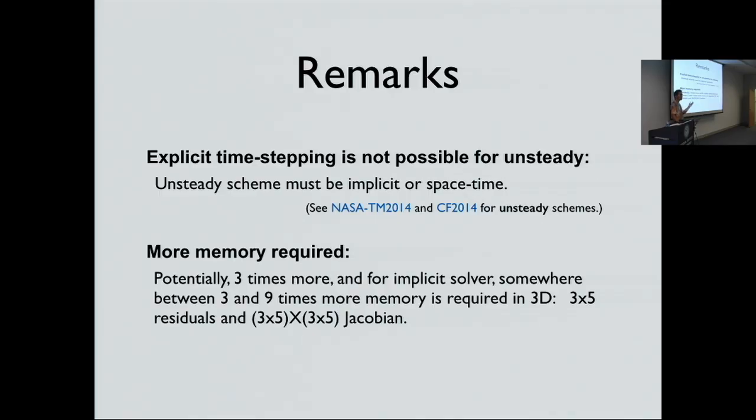The upwind flux for the hyperbolic viscous term is not actually upwind biased. Well, it's upwind biased, but this system represents an isotropic wave. So you upwind the left and right, and you end up with a symmetric flux, as opposed to the convective one where you have u plus or minus a, which is not symmetric. But it doesn't have to be upwind. If you have a good scheme for implicit, whatever it is, you can apply that to this system.